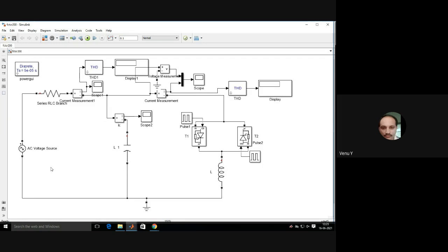If you go for the design, then you need to study the reactive power variation from no load to full load. From no load, you can obtain the TCR rating. From full load, you can obtain the fixed capacitor rating. So that altogether, you compensate the transmission line at no load and also at full load.